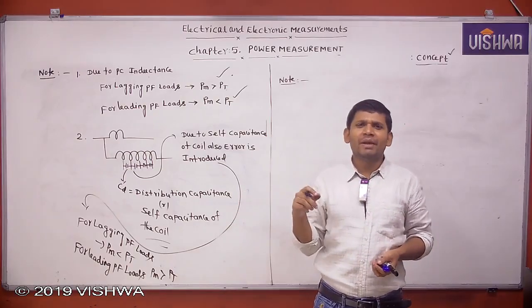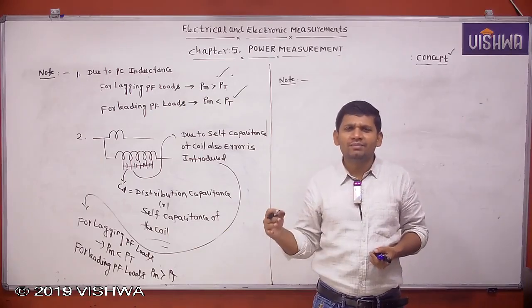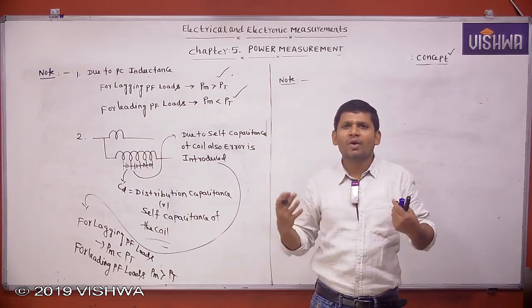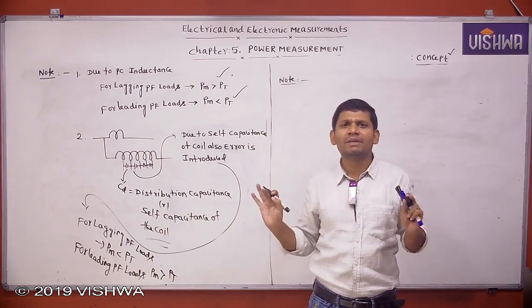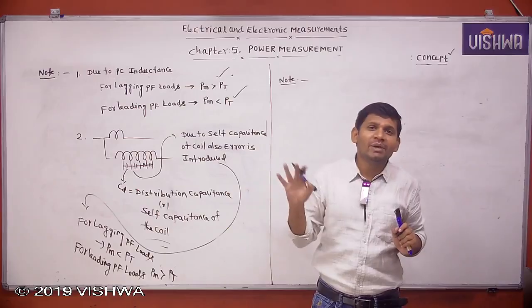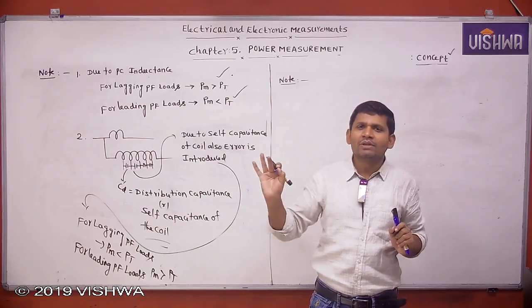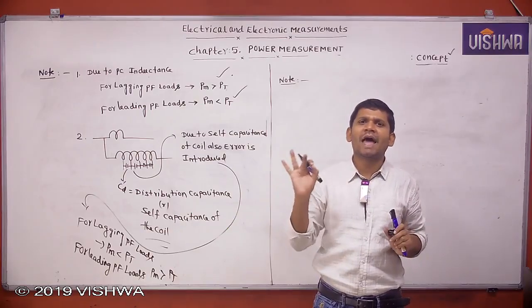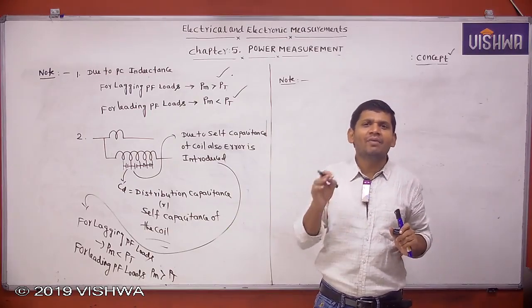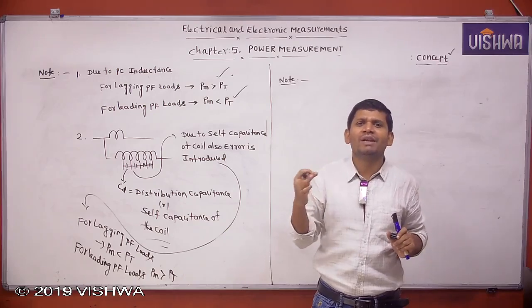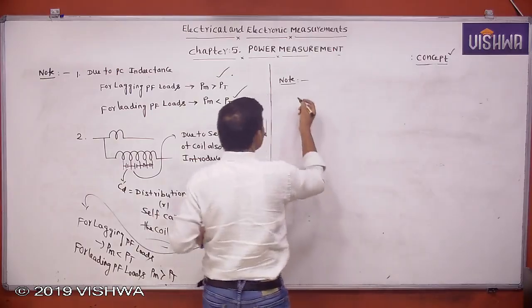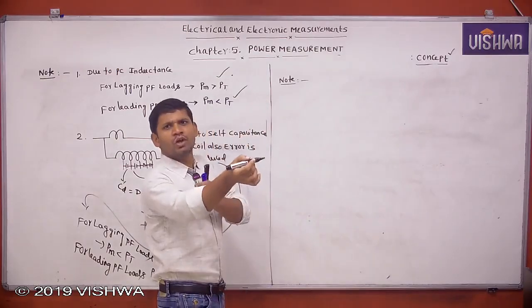During power measurement, the wattmeter cannot see whether the supply consists of harmonics or not. Whatever the input we give, the wattmeter measures the power. But what power it can measure, I told already. For single phase power measurement, in general a wattmeter measures the active power, and it is an average power measuring and average power indicating meter. Understood?